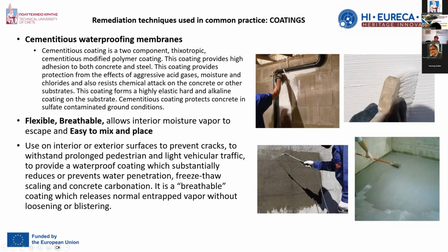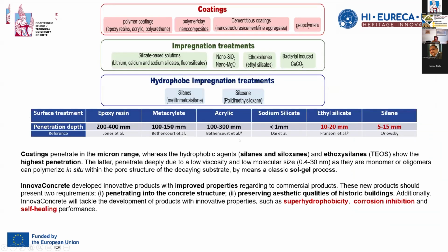One, of course, of the drawbacks of those coatings that were proposed for the modern concrete maintenance is that when they applied, they totally changed the appearance of the surface, and therefore, in order to protect the historic concrete, we have to design some coatings which do not alter the aesthetic parameters of this concrete surface.